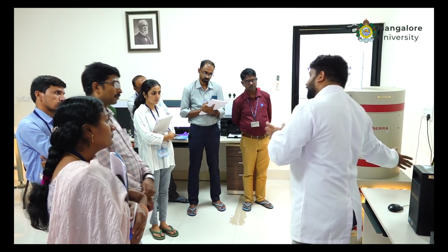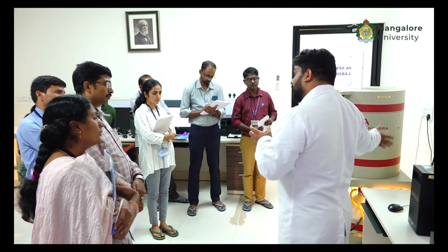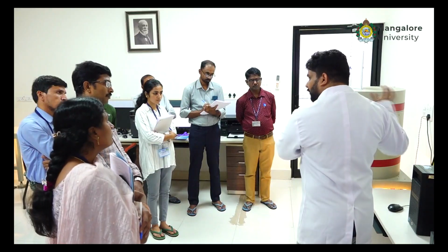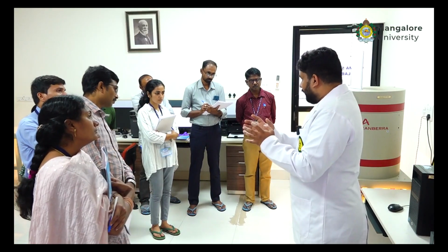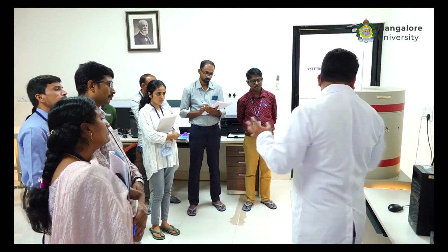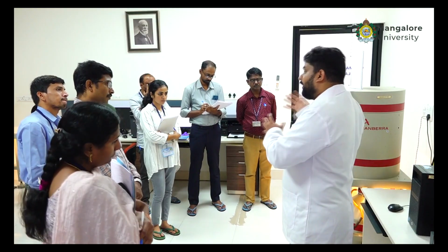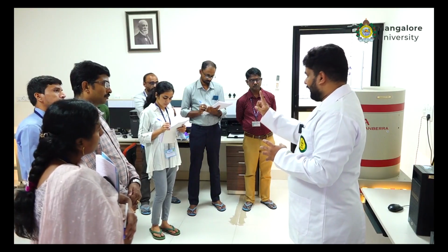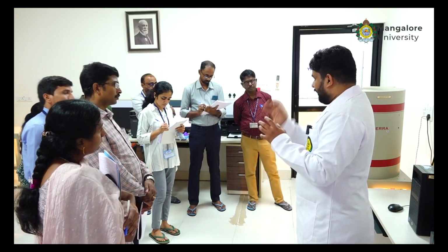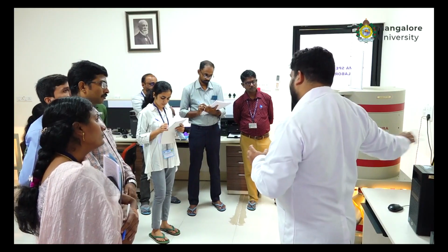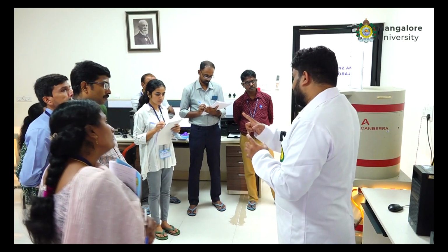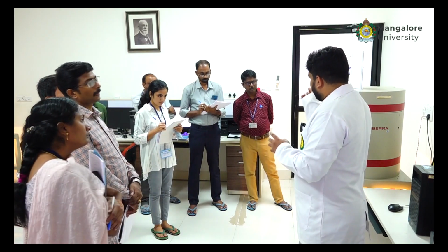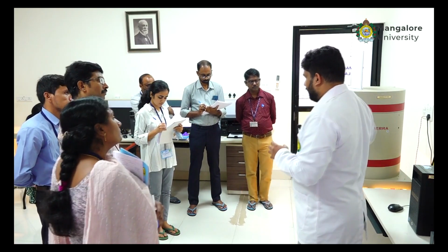So we have 32,000 channels, so 32K MCA. 32,000 digital boxes are there, in which I can assign one box to be equal to whatever I need. We have assigned here one channel equal to 0.25 keV. That means four channels equal 1 keV. Understood? So this system can distinguish between 1.25 keV and 1.5 keV. So a resolution of 0.25 keV is there with the system.